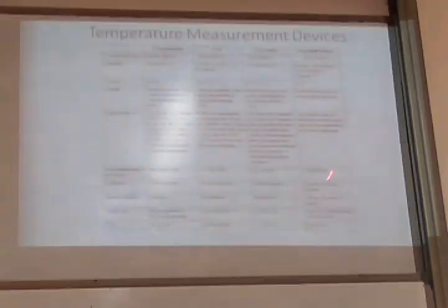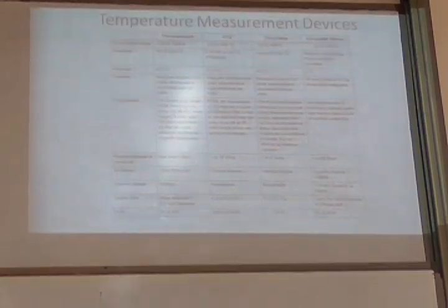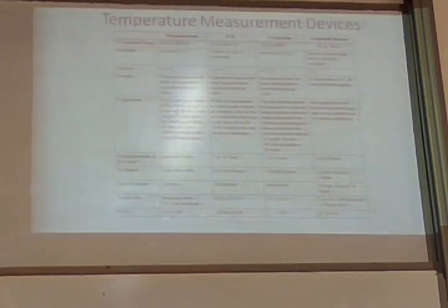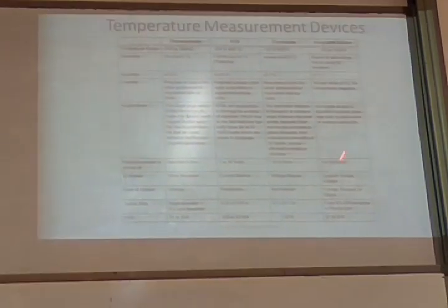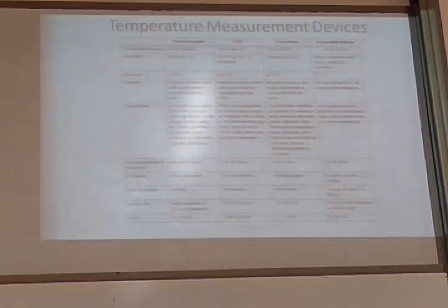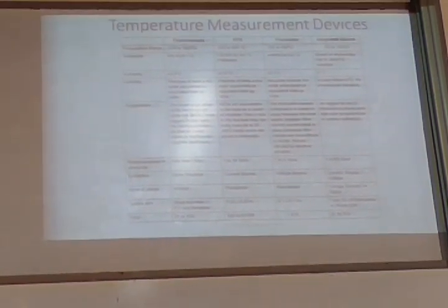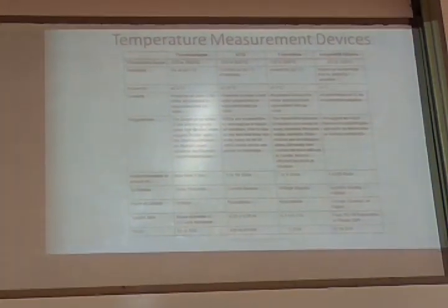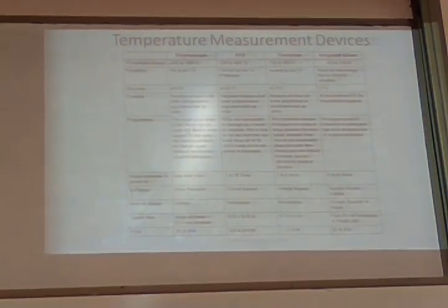Whereas integrated silicon, that's very cheap. But of course, the disadvantage is it takes up to 1 minute to show you the actual temperature. Very, very cheap, but it takes a little extra time. That's why for industrial applications, sometimes you will think twice before using integrated silicon. On the roadside, sometimes you will get digital thermometers, which are sold for less than 100 rupees.